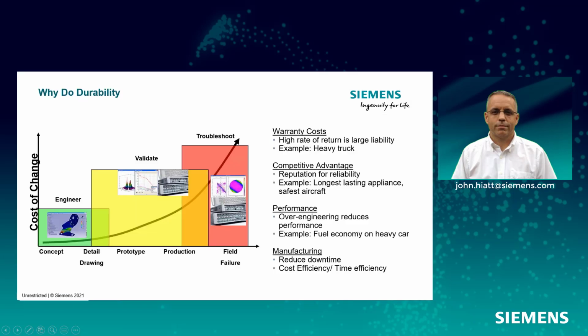Well, why do we do durability? Fatigue is a big part of durability, and the main reason we do this analysis is we don't want to wait till things break. We want to understand if they're going to break before we make them. And obviously, the way to do that is to have good models and good sign-off tests, so validation tests.